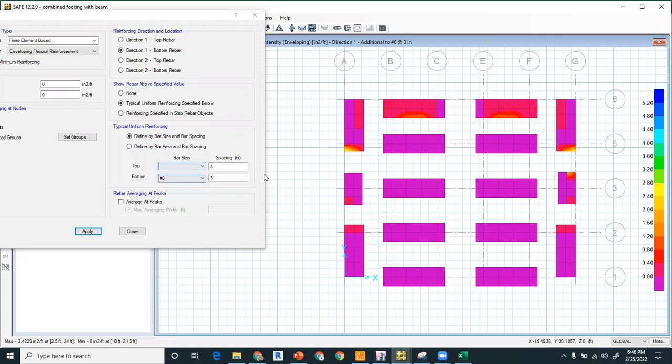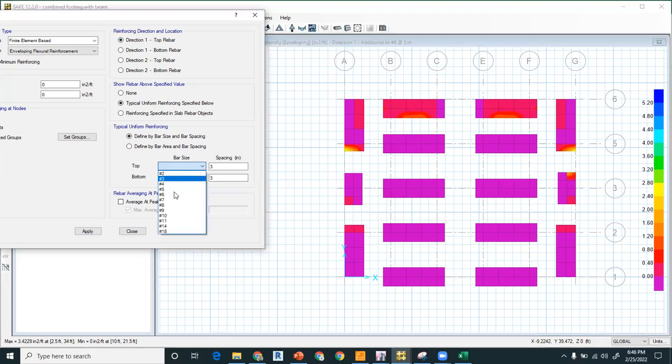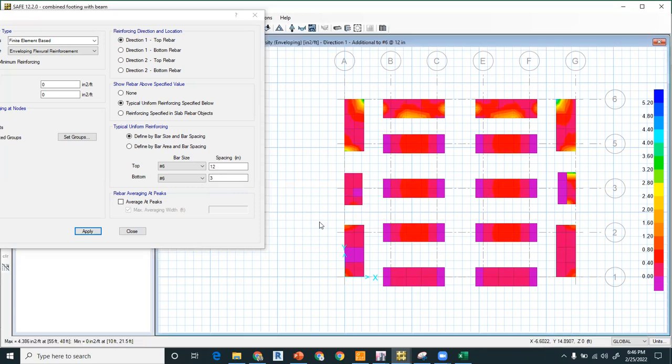So if I check the reinforcement, it is still asking for too much reinforcement at the bottom. So you can increase the thickness or decrease the spacing of the footing, right? For the top reinforcement, if I use number 6 bar at 12 inches, it is not working, right? So you have to decrease, because I have designed this structure using the UBC load